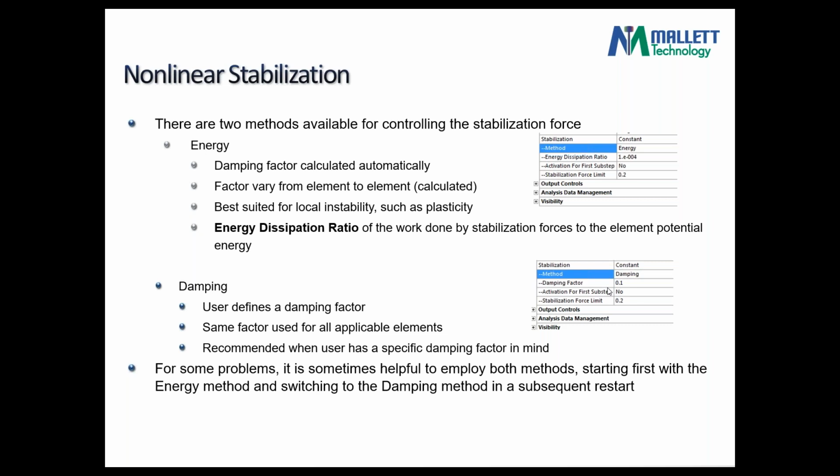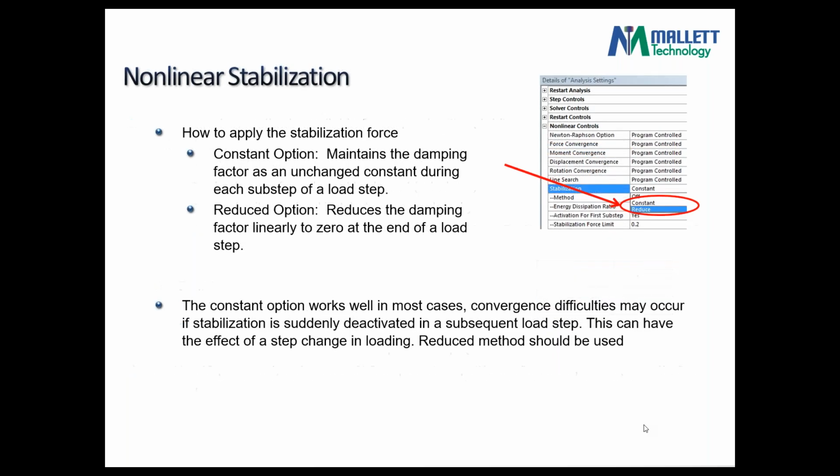Most probably, when you do nonlinear analysis, you will start to gain knowledge in this area. You know what kind of damping you use in the system. There are some defaults you can rely on, but what I recommend is trial and error and building experience. This is very challenging. In some applications, you might also apply both methods. You probably start with the energy method because it's localized to different parts of the structure, and switch to the global method through some kind of restart analysis. That's what we recommend.